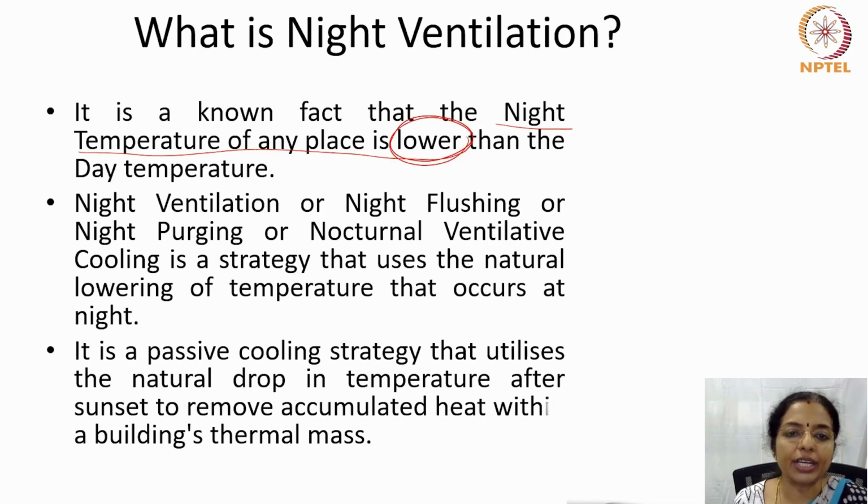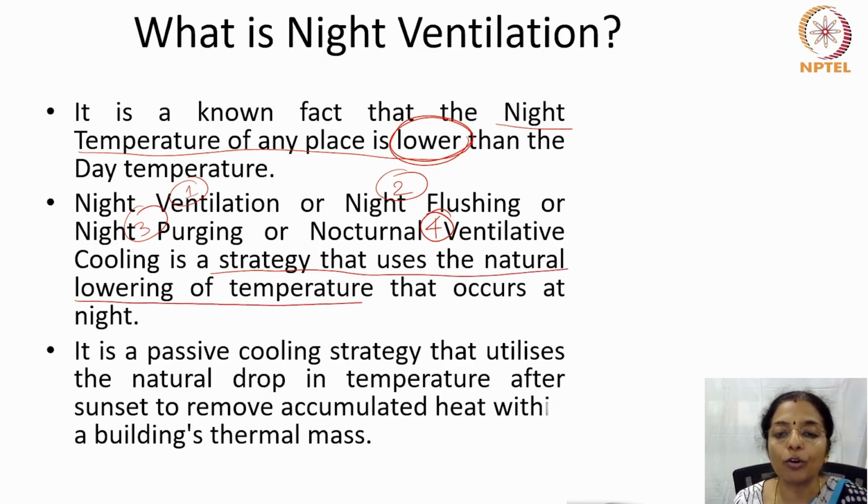Night ventilation, night flushing, night purging or nocturnal ventilative cooling, these are all the same thing, and it is a strategy that uses the natural lowering of temperature that occurs at night. It is a passive cooling strategy that utilizes the natural drop in temperature after sunset to remove the accumulated heat within a building's thermal mass.